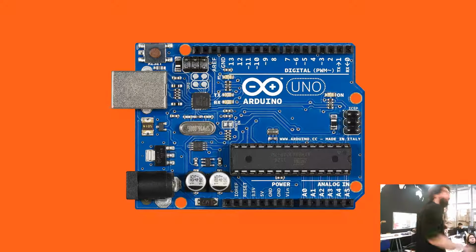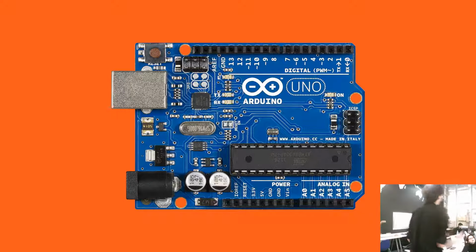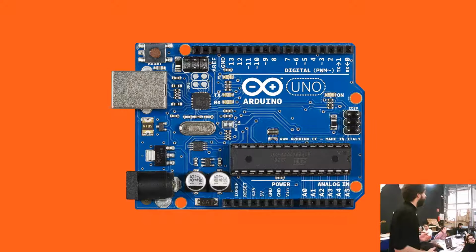And then we just have a bunch of convenient pins and outputs and inputs where we'll connect things. And we have things like a USB connector, and because the chip cannot talk USB, we have a serial to USB converter, and we need the clock, and we put it there. So it's like a workbench where to play, you know? And it's also what we can call a blueprint, because it's a design that we can take inspiration from, we can use, to then build our things on top.